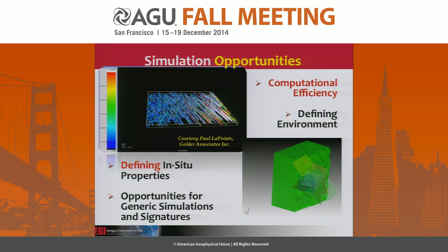And it kind of makes sense. If you look at it, both of those are methods that are causing viscous losses in relatively narrow features. And if you have a secondary fracture with a smaller aperture, that smaller aperture is going to cause additional viscous losses, either caused by rate and or pressure, and it's going to inhibit the fracture from growing into those secondary features. And so this is one of the tools that can allow us to control the morphology of hydraulic fractures.